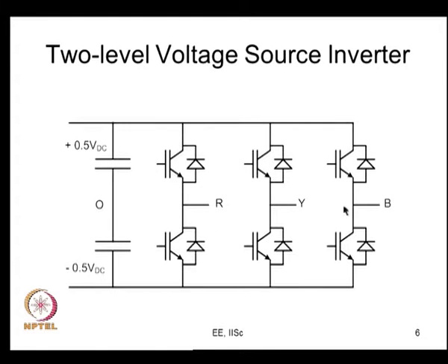So, the loads are connected, and there will be fundamental and harmonic components also. As you will see, the effect of the harmonic components on the switching loss would be negligible, because the harmonic currents themselves might be negligible compared to the fundamental current when you are switching at fairly high frequencies. And of course, switching loss is mainly a concern at high switching frequencies. This is the load, and this is the DC side, and the DC source is connected there. How much DC link current and capacitor current flows, we had seen previously in an earlier module.